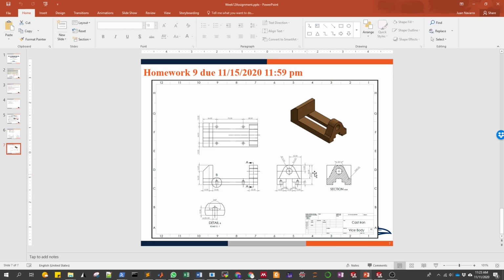These are the main types of views that you're gonna be using as mechanical engineers, as professionals. And the technical information is, for example, the material of the part, who modeled it, the date, who revised, and the name of the part, which is gonna be marked here in the lower table of the blueprint.